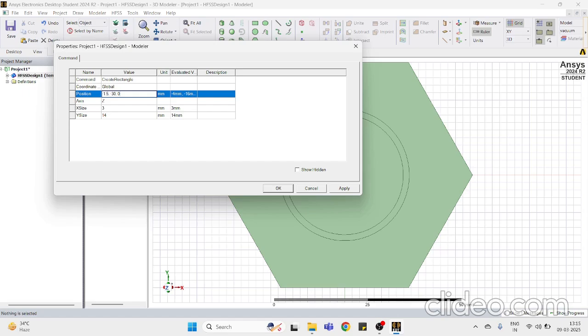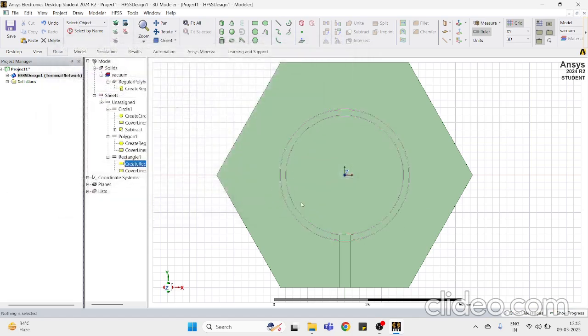Like this thickness is 3 mm, and the end point that it goes to is here, and that end point, if you calculate the position with respect to origin, it's minus x by 2, and that's minus 1.5, and the position in z will be 1.6 mm because it's on top of the substrate. Now I'll just press OK, and here you see this.